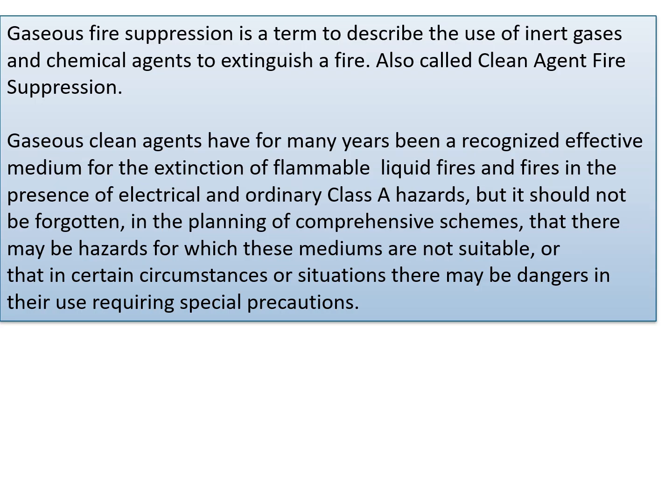Gaseous clean agents have for many years been a recognized effective medium for the extinction of flammable liquid fires and fires in the presence of electrical and ordinary class A hazard. But it should not be forgotten in the planning of a comprehensive scheme that there may be hazards for which these media are not suitable, or that in certain circumstances there may be dangers in their use requiring special precautions.